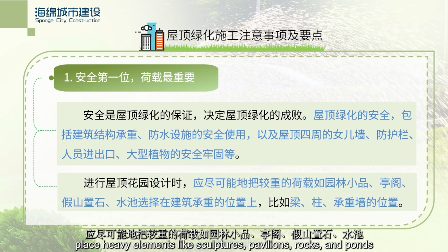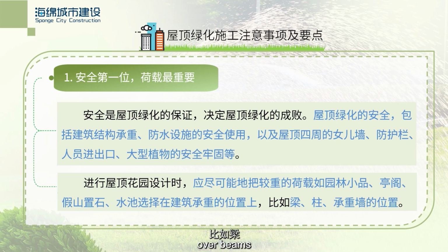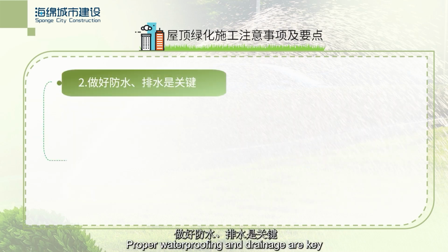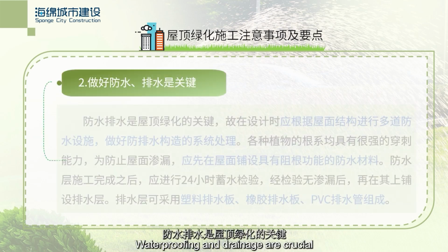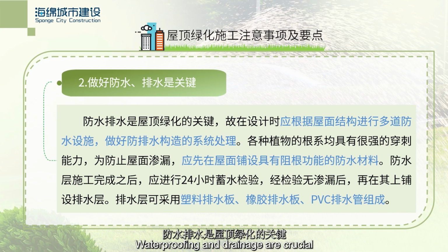Place heavy elements like sculptures, pavilions, rocks, and ponds over beams, columns, or load-bearing walls. Proper waterproofing and drainage are key. Waterproofing and drainage are crucial.